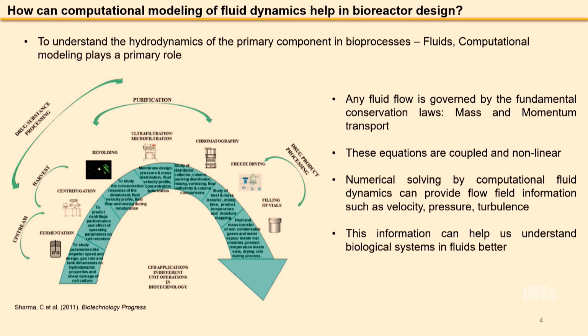So firstly, computational fluid dynamics is a technique where the fluid flow governing equations such as the mass, momentum and in some cases energy transport are solved numerically, because these equations are non-linear and coupled. This numerical solving will help us to provide flow field information such as the velocity, the pressure and turbulence which is prevailing in the system.